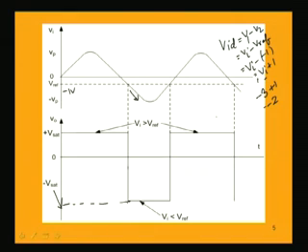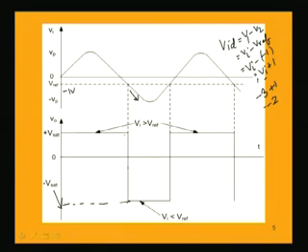So, here we are getting again a digital voltage, that is, it is jumping between only two levels, plus 14 and minus 14 volt. Here we have seen one difference from the earlier one. If we consider the width of the pulse, that is the portion for which it is positive and the portion for which it is negative, that is not the same. This pulse width for the positive one and for the negative one is not the same; it is not symmetrically positive and negative. That can be varied by varying this V reference voltage. That example we have seen.